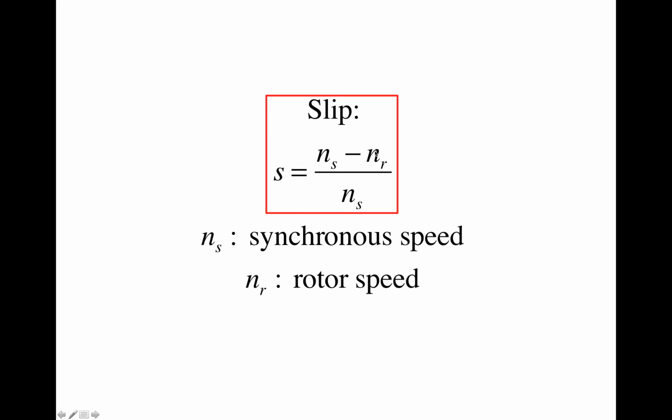So when Nr, the rotor speed, equals zero, Ns subtract zero equals Ns. So the relative speed is exactly the synchronous speed, and the slip equals 1 under this scenario. So when the rotor is locked at the stationary position, the slip is unity. That's slip, and we're going to use the concept of slip in the following sequence of videos.